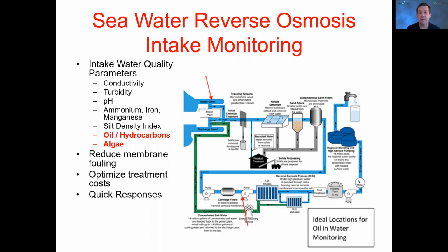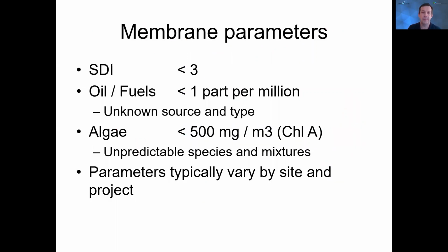Because the response of these devices is instantaneous, it can be quite easy to optimize the chemical additions or the DAF usage based off their indications.